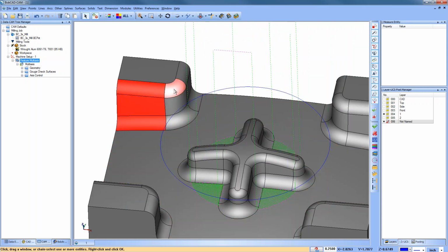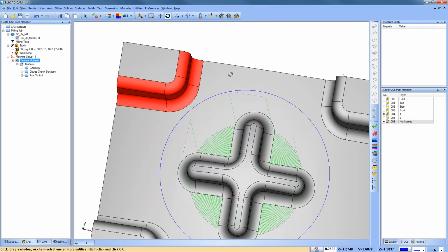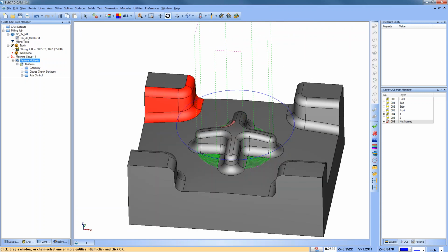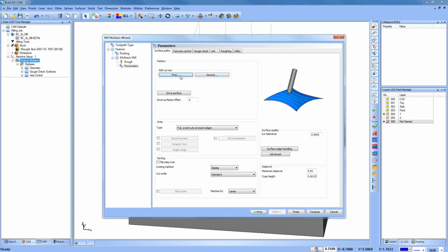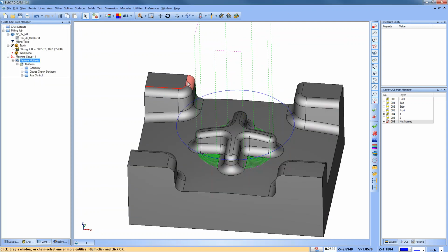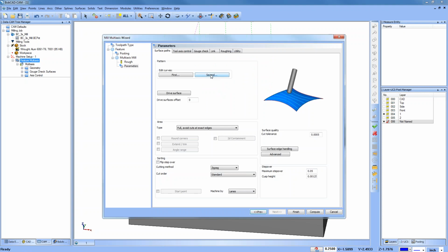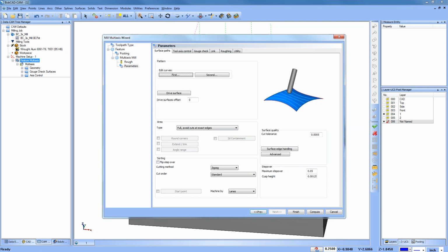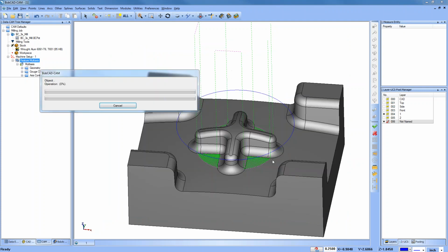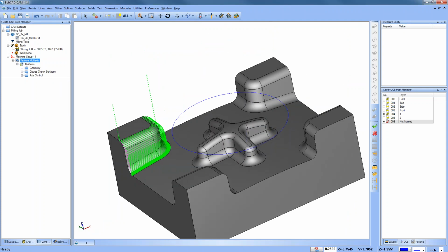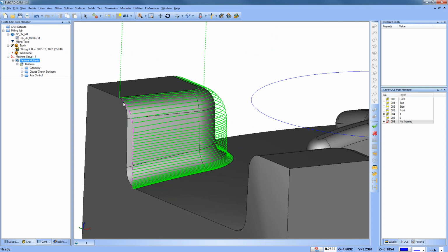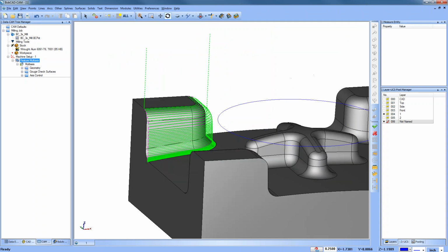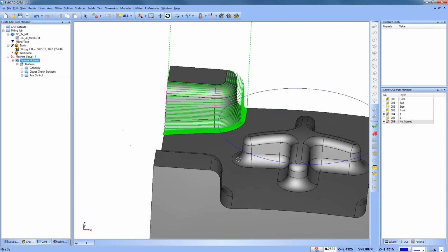So I'm going to select these curves here. These are the surfaces that I want the toolpath driven along. All right, so those are my drive surfaces. Okay, my first curves, I'm going to pick the top curves here. And you can pick surface edges or wireframe. Either will work. Second curves, these are going to be the curves down here at the bottom. Go ahead and space bar to that. And then we'll compute this here, and we'll see we get our toolpath blending from one side to the other. All right, so this is a morph strategy, an example of a morph strategy.